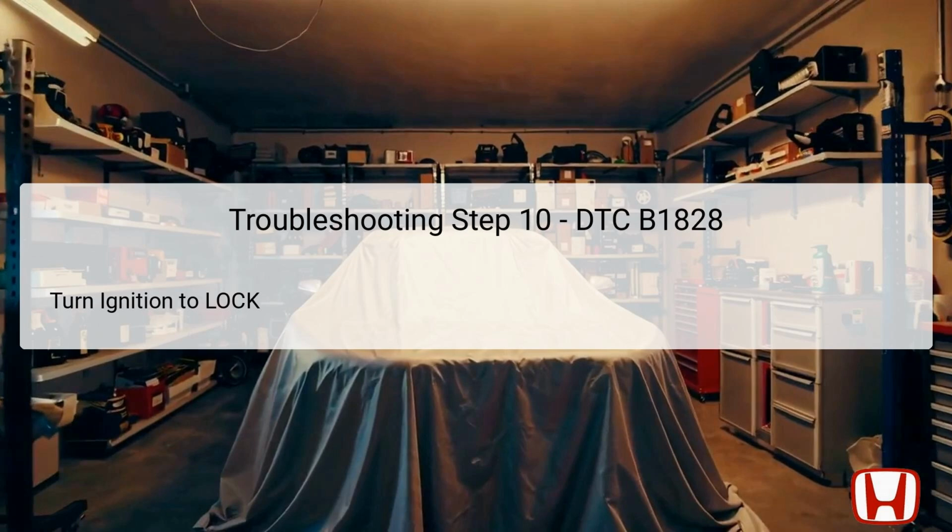This step also allows for the necessary cool-down period for electronic components that may have been under load during previous tests. Always ensuring that the ignition is set to lock reflects good safety practices whenever working on automotive electrical systems. By cautiously following the proper sequence of powering down systems, you minimize risks of inadvertent shorts or shocks during troubleshooting.